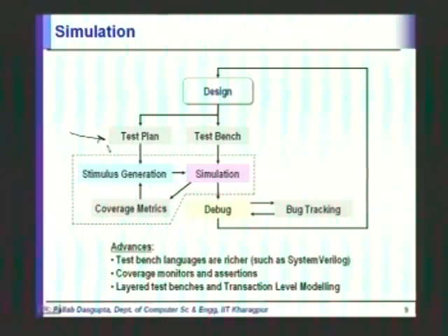Now when we are actually running the test bench, we need to make sure which of those tests have been covered, right? So how is this test plan used? It is used to generate the stimulus. Okay. Now what is the stimulus? These are those tests which the test bench will drive into the simulation.